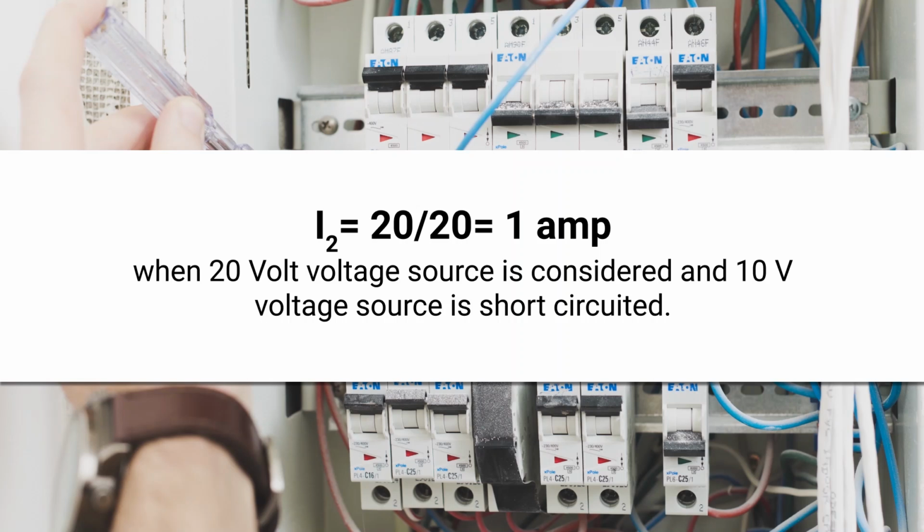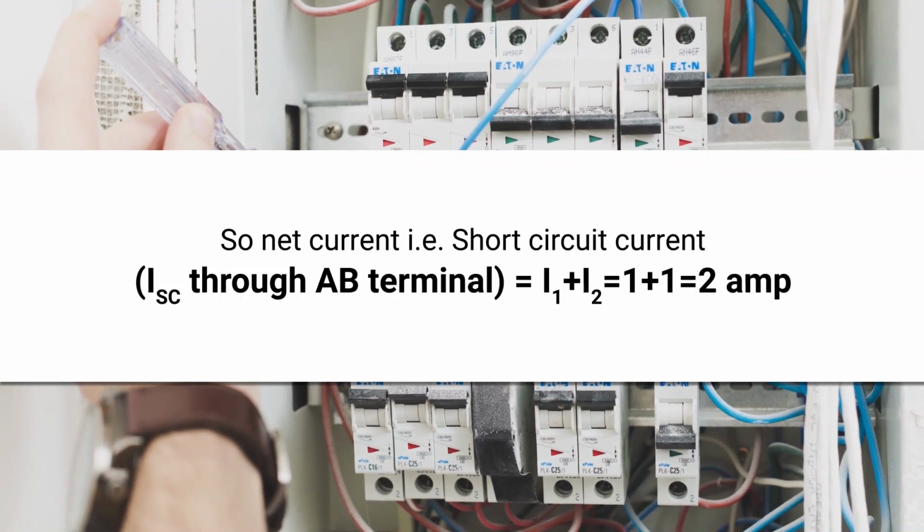So when you are considering this 10 volt source, that current I1 is flowing in this direction from A to B, that is 1 ampere. When you are considering this 20 volt source, then the current is again 1 ampere, because 20 divided by 20 is 1 ampere, and at that moment the current is also flowing from A to B. So what the superposition theorem states is that it will be equal to the algebraic sum. The currents flowing due to these two individual voltage sources are in the same direction. So ISC can be written as ISC is equal to what? I1 plus I2.